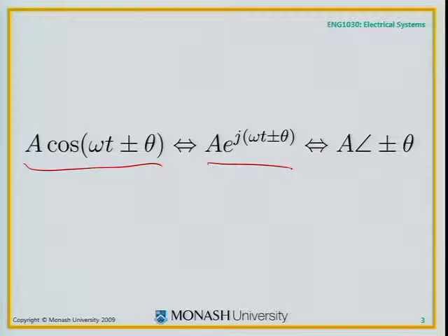But it's going to turn out that it's easier to deal with these quantities. If we track sinusoids around the circuit, it's trigonometry. If we track complex exponentials, it's complex arithmetic. So it's a little bit easier to do the analysis with complex numbers.